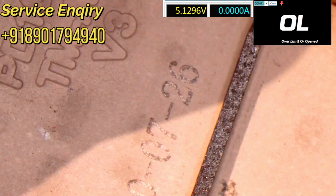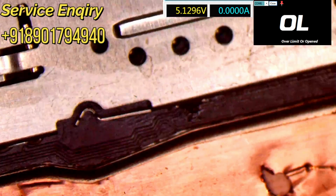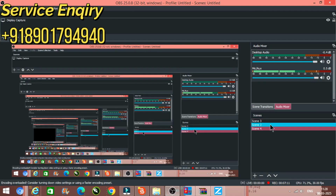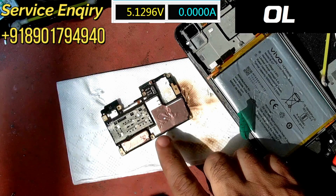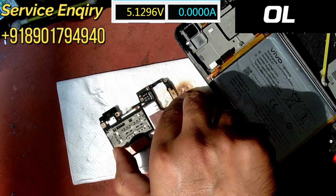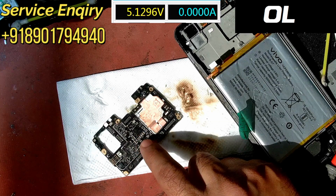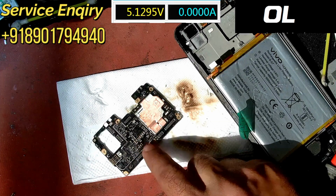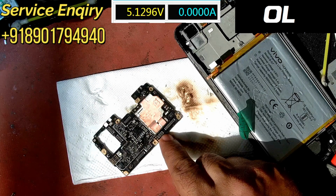Now check the other side of the motherboard for any work. Let me show you. There is no work on the other side. Let me show you in the main camera. Look at this, there is no work on the other side, only on that side, near the power IC. Right now VPH is okay and VBAT is also okay according to the multimeter in diode mode.